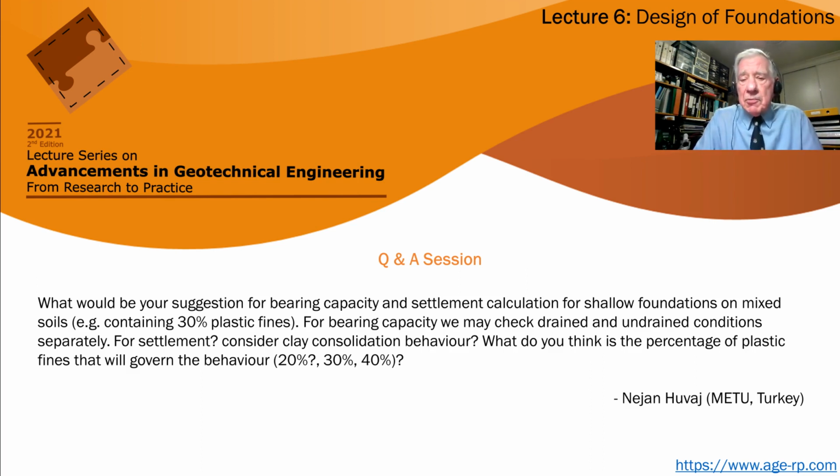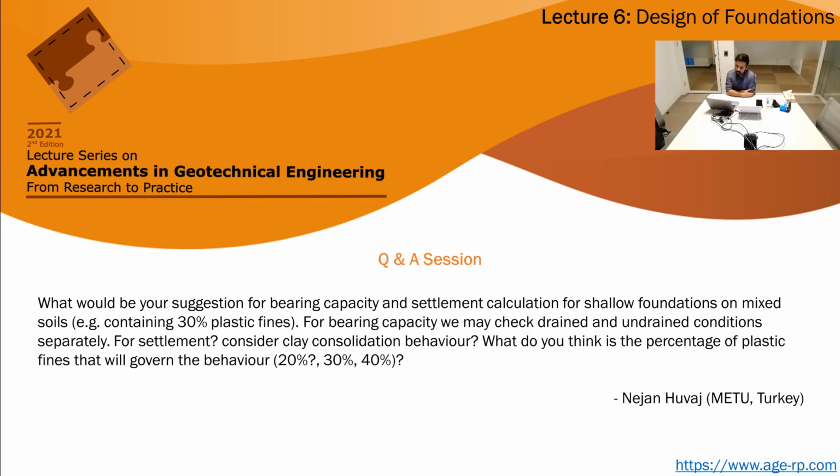This is one of the attractions of methods such as CPT, that it doesn't necessarily demand that we categorize the soil as a sand or a clay, because these days the cone test in particular will tend to categorize the soil itself and give us the necessary correlation. So I'm sorry, I can't be more specific than that, but never rely just on one method of settlement calculation.